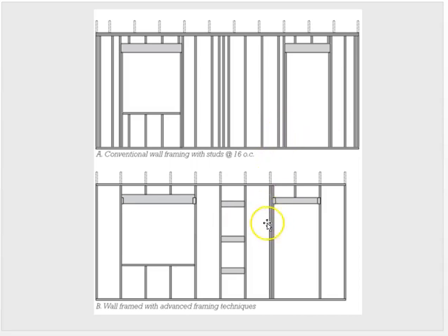This must be a stud joining here. So this is a double or something, maybe even a triple, I'm not sure what's going on there. But basically reducing the doubles to singles. And then here, where that wall was coming in, and we're going to look at this in more detail. I'm going to jump back one. No, we're going to see it on the next slide. Where the interior wall meets, we have this kind of continuous studs to meet it. Here we get rid of the continuous studs and we make this kind of ladder instead. And we'll see this detail in the next slide, what we're trying to accomplish exactly.